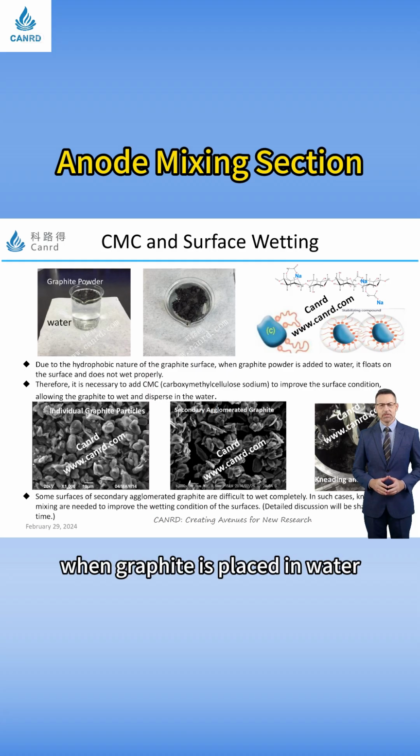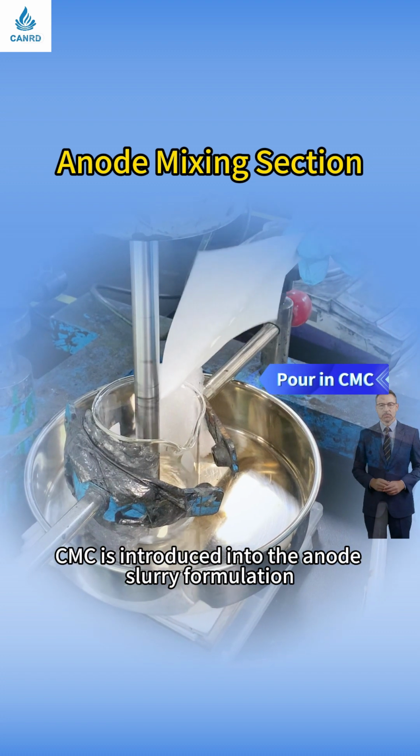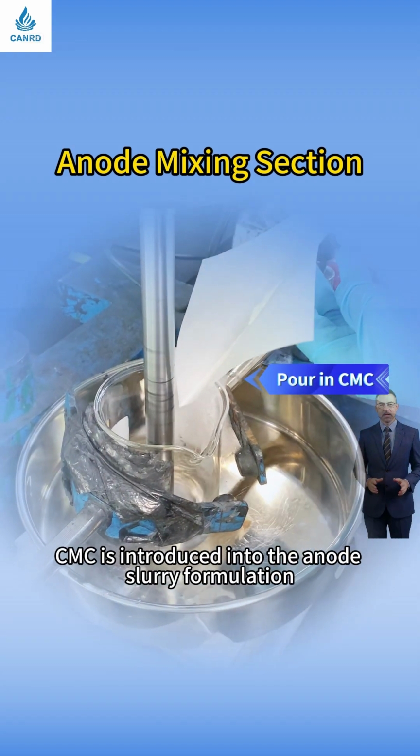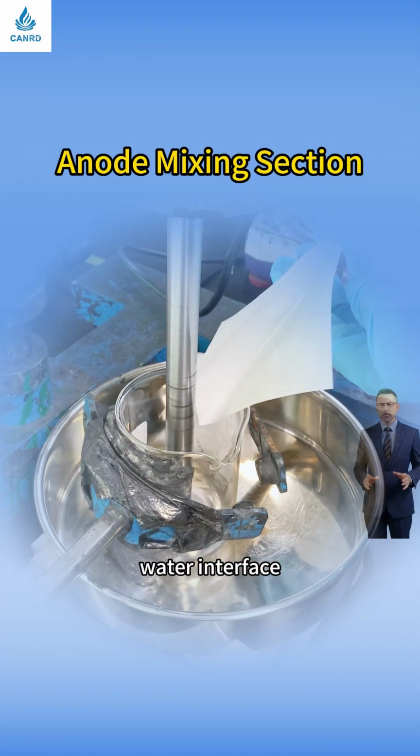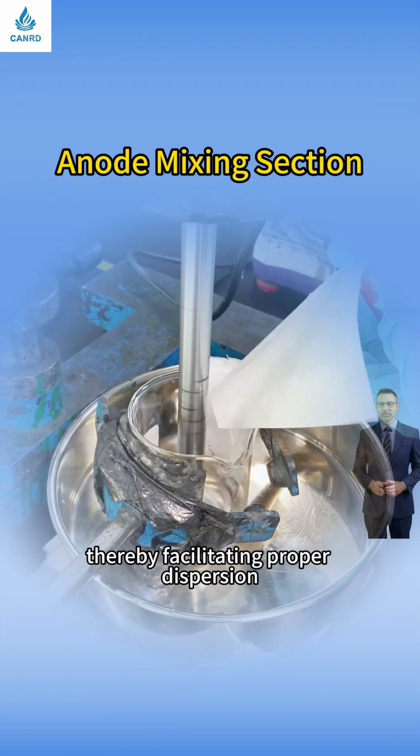When graphite is placed in water, it generally floats on the surface because its surface is hydrophobic. To address this issue, CMC is introduced into the anode slurry formulation. The role of CMC is to enable effective wetting at the graphite-water interface, thereby facilitating proper dispersion.